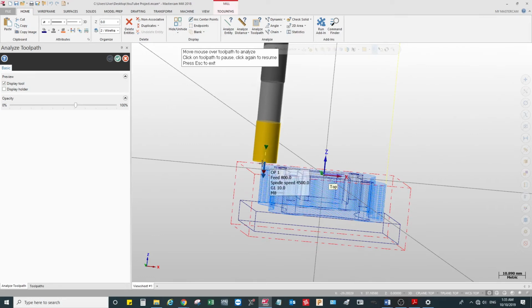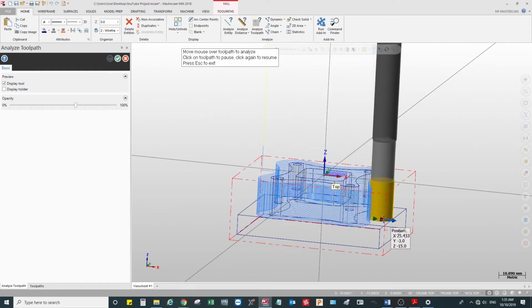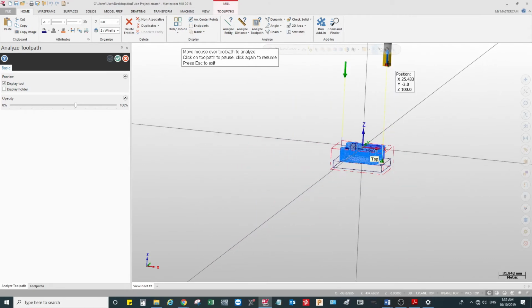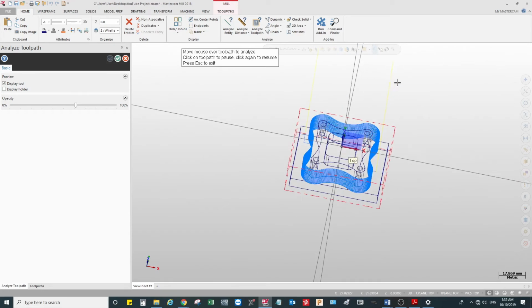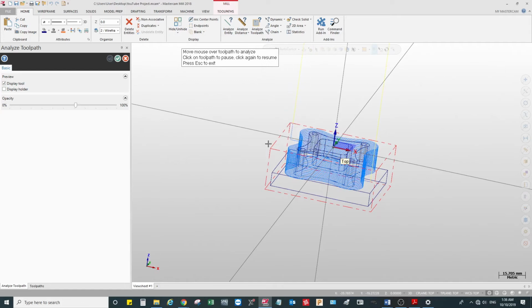If you go and have a look at the drawing in here, you can see the left view. You can see 15 millimeter, so that's exactly what it picked. Okay, so moving on to the next, home position. You don't have to do anything in it, so it's all good. Coolant, it's already on.